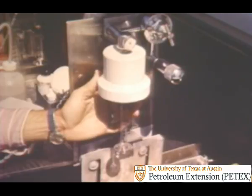This equipment is used to determine the mud's API filtration rate. The mud sample is placed in the white container and is put under 100 pounds per square inch of pressure for 30 minutes. The liquid part of the mud, the filtrate, runs into the graduated cylinder below the white container.